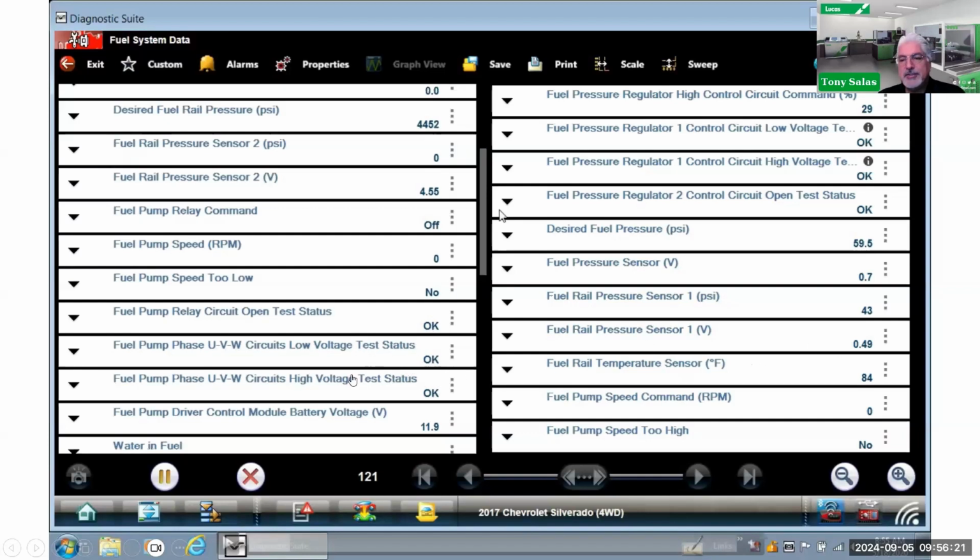However, though, he's telling me right off the bat what's the status. In other words, he's doing testing on it, because that's his job anyways. He's supposed to be doing circuit tests to know what's going on. So that helps me a lot when I do my diagnostics here, because again, I can look at the status of them just by looking at the PID data to see if it's okay.